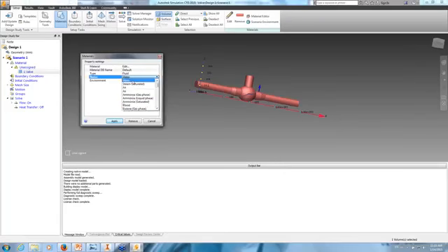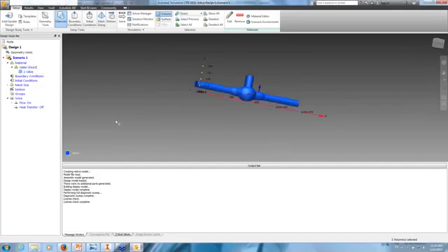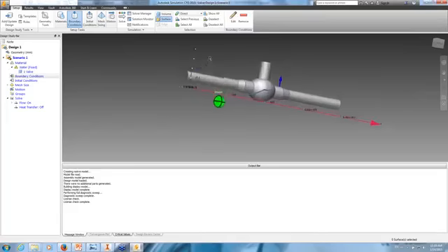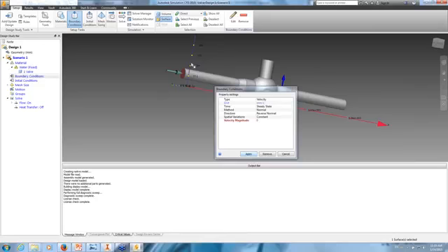In this case we have water, and I'm going to click apply. So I've set the material. I'm going to click next on boundary conditions. This one's going to be a simple one, and what happens by default is it switches to surface. So if I click on it, it's only going to select that particular surface. I'm going to click on that surface, and I'm going to grab the edit from here, and in this case I'm going to set inlet velocity.